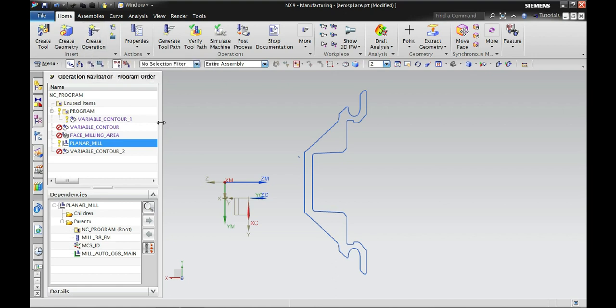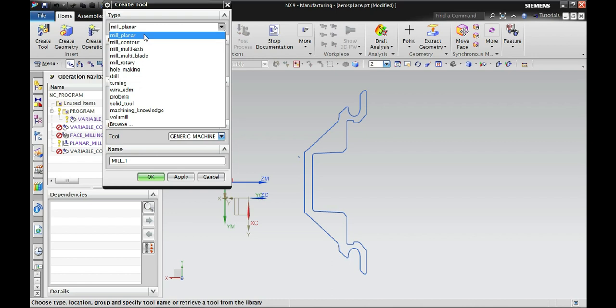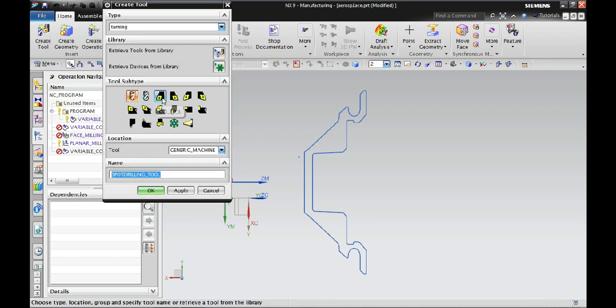In all the previous videos, I put in a step-by-step on how to select the toolpath, how to apply the turning and milling features for a mill-turn machine. Now you want to select its mill planner, you can select all the milling tools, and you've got to select the turning. As you can see in the legend here, it will explain to you: this is a left-hand tooling. What is turning? It's an 80-degree diamond. It's a right-hand tooling, 80-degree diamond. If you want to use it as shown on the legend, the symbol, you can select this layout for a main spindle or subspindle.